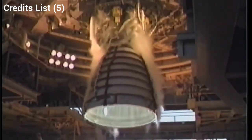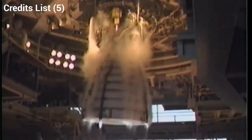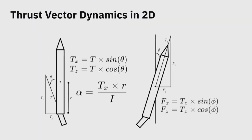In this project, I developed a way to artificially throttle solid fuel rockets by vectoring the thrust away from the ground. Nearly every rocket produced today has an engine gimbal that allows for thrust to be vectored. This vectoring is what controls the rocket's orientation as it travels through the air. When thrust is vectored by a significant amount, the vertical component of thrust decreases, providing an effect similar to throttle control without actually altering the thrust output.